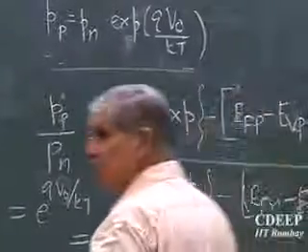So when I look for transport, the first thing I will show is where my Fermi level motion is, and which way it is going. If I see the Fermi level slope, I know current is flowing. This is the technique. So device to circuit, how do I look? What happens in the device and what will happen externally, I can correlate now. If I externally apply bias, which we have hopefully explained in the lab, you find why currents flow when you apply bias, otherwise they do not. Essentially the Fermi level shifts whenever there is current. Is that clear? This fact proves my point that Fermi level movement is the cause of current, which is very crucial.